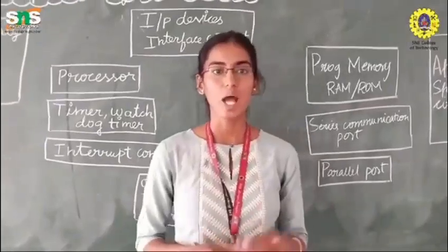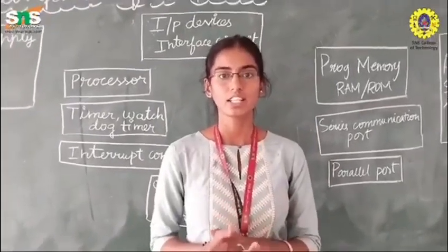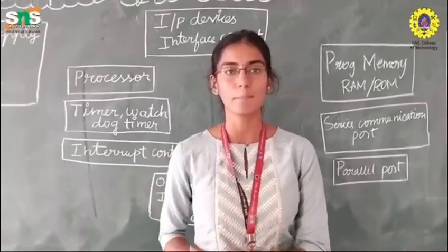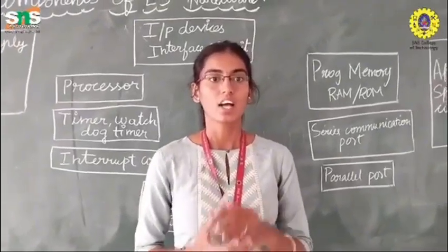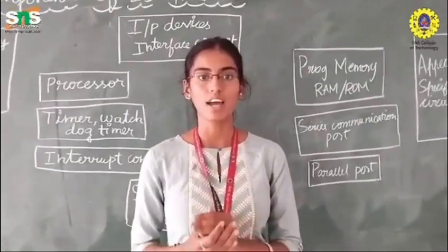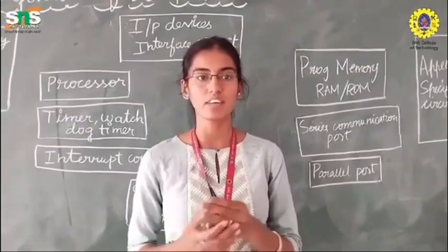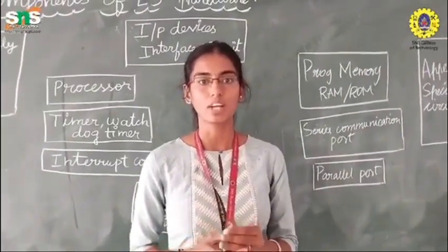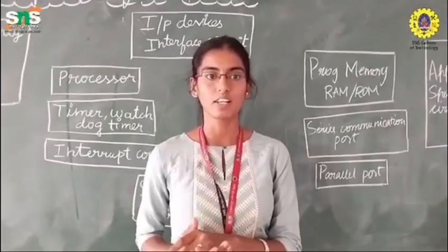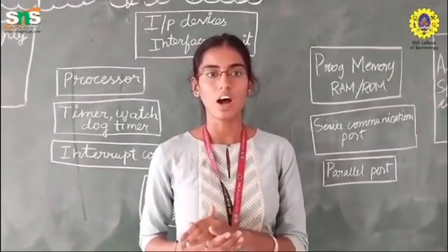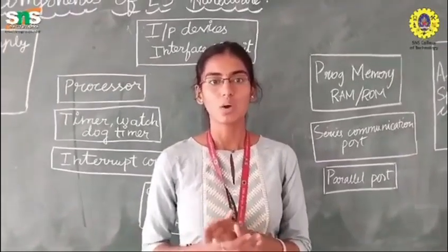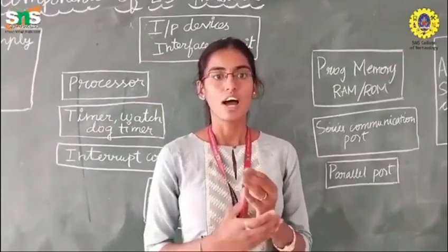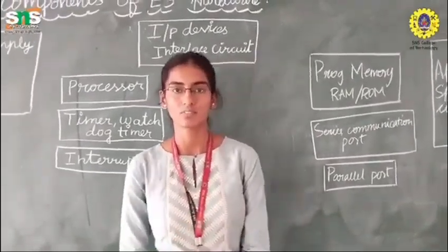Timers are used in applications requiring the creation of a delay before the execution of a specific function by the embedded system. On the other hand, counters are used in applications where the number of times a specific event takes place needs to be tracked. Up counters count upward from the starting value, while down counters count downwards to 0. Counters are integrated in the form of register type circuits.